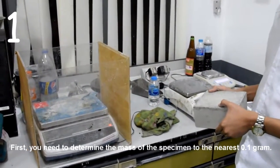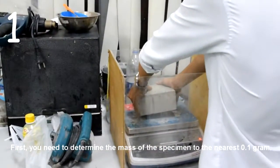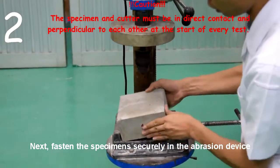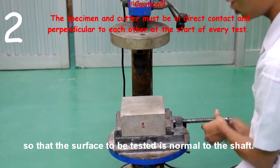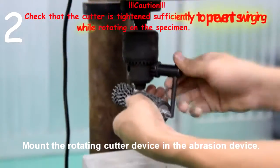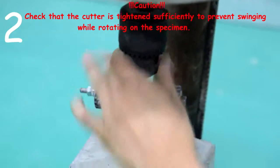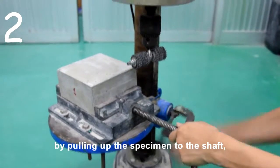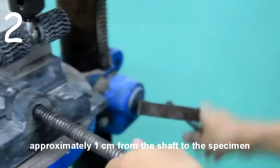First, you need to determine the mass of the specimen to the nearest 0.1 gram. Next, fasten the specimen securely in the abrasion device so that the surface to be tested is normal to the shaft. Then, mount the rotating cutter device in the abrasion device. Adjust the level of the specimen by pulling up the specimen to the shaft, approximately 1 cm from the shaft to specimen.